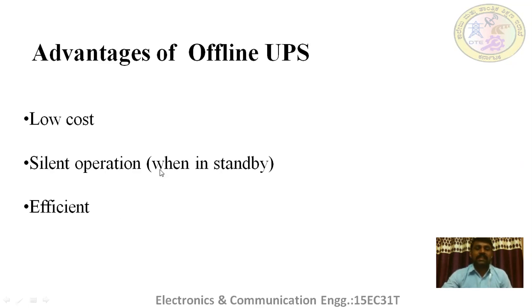As I said, this is used just as a standby. We can use the UPS when we require power for the load. There is no necessity to use this continuously. Also, this is efficient, meaning it is capable of providing AC supply to the loads as in the case of online.